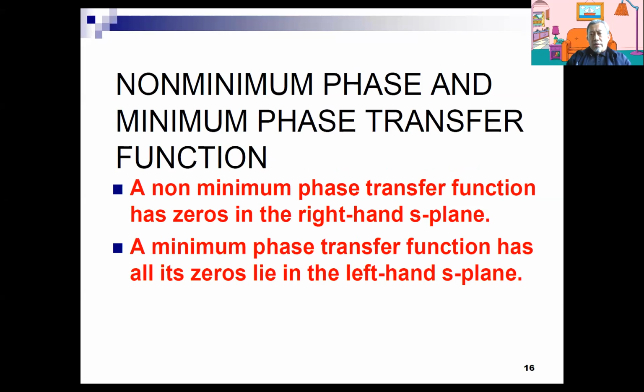Discrete is the data from the continuous time. We use sample and hold, like a switch. If you sample at 1 second, the switch will act every 1 second to capture the data.